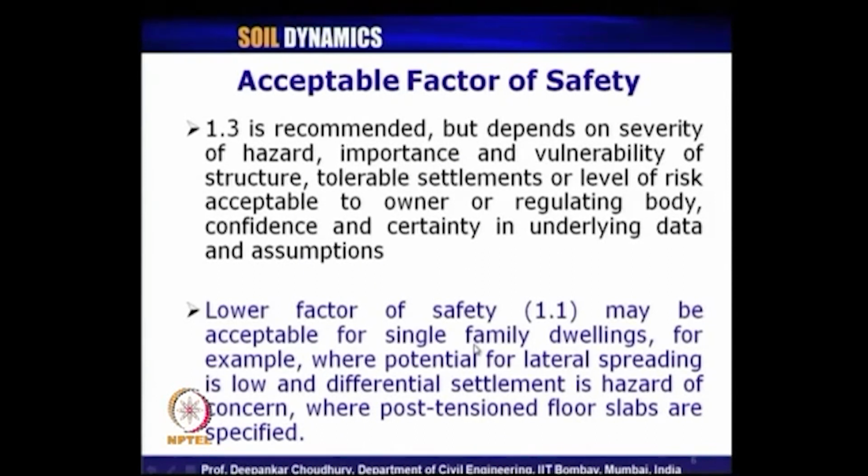And what are the acceptable factors of safety for design against liquefaction? A factor of safety of 1.3 is recommended for important structures, whereas a lower factor of safety of 1.1 can be used for less important or small buildings like that.